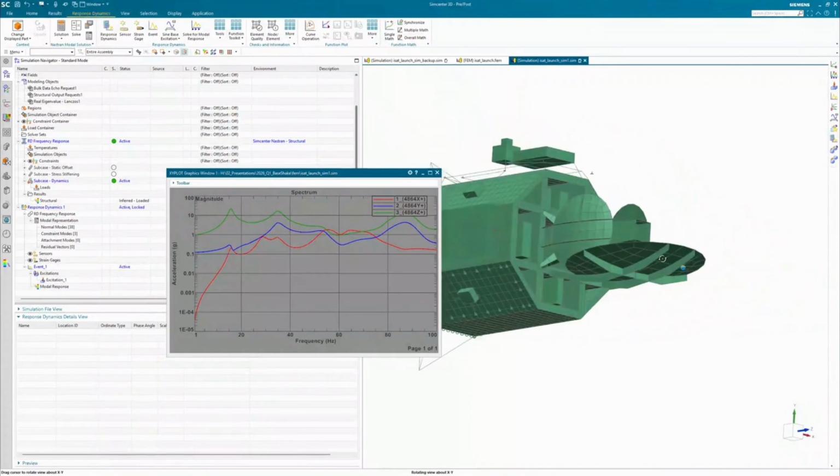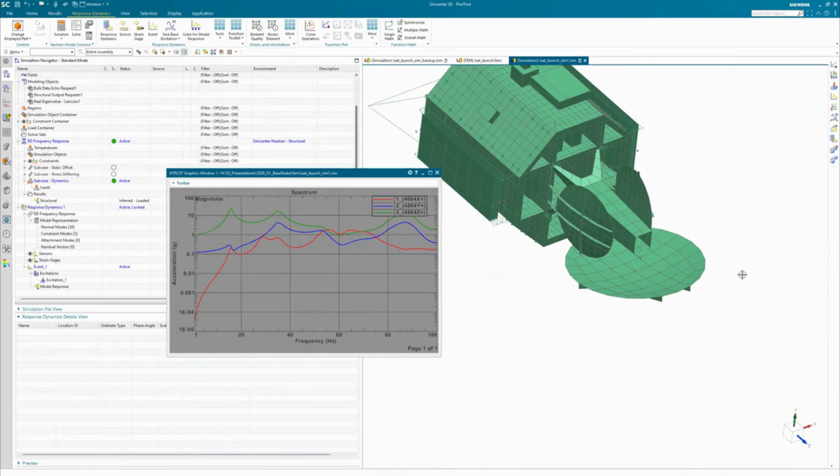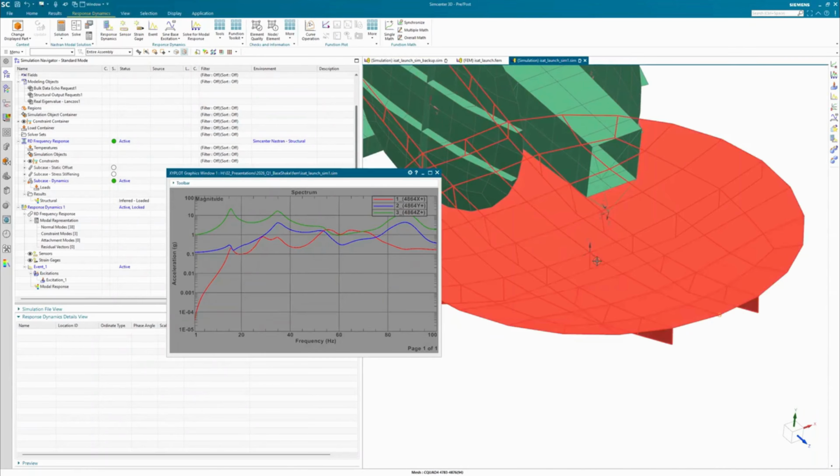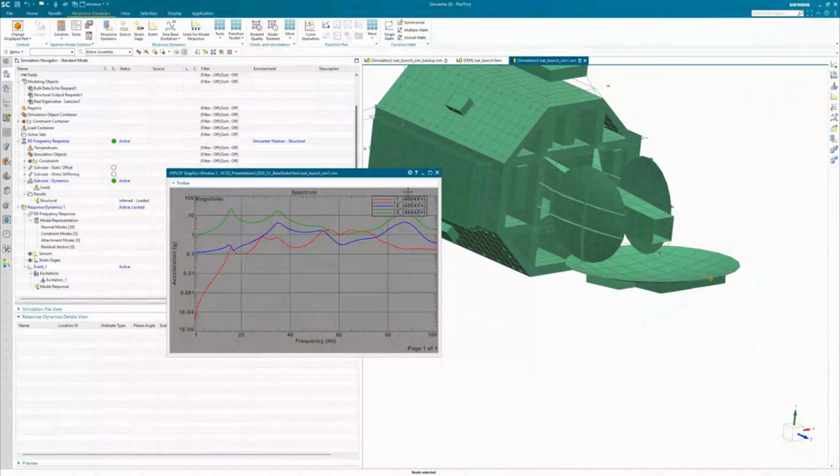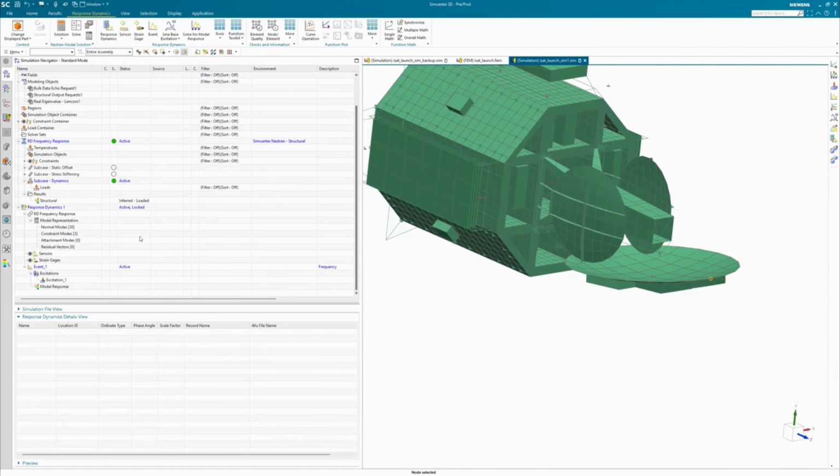All of the xy output data is going to be in whatever the node's output coordinate system is. So for this node, it's actually defined for an output coordinate system where z lines up with global y. So the output that we're expecting is the z to go to 1 as you go to 0 hertz. We'll hold on to that plot for later.